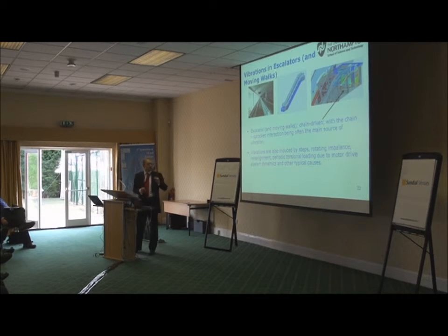In addition, we have other causes: moving steps, rotating unbalance, pulleys which can be misaligned, and torsional loading due to the motor drive, and typically any other cause which you could see in any other machine. An escalator is a multi-dynamic system typically consisting of hundreds of elements. So everything moves.